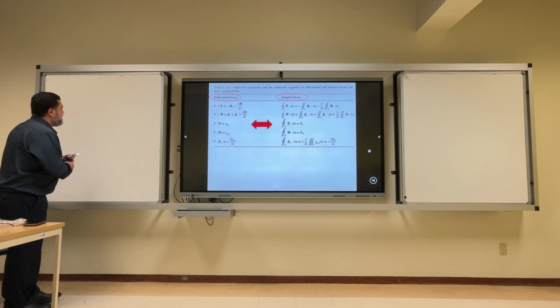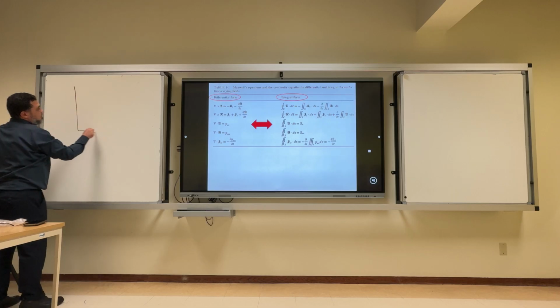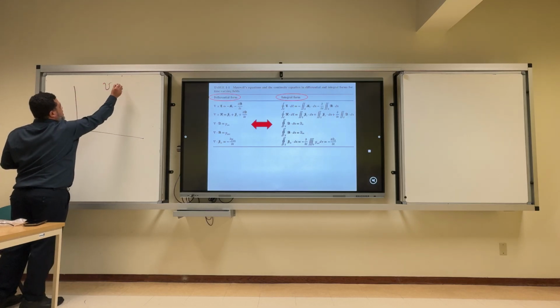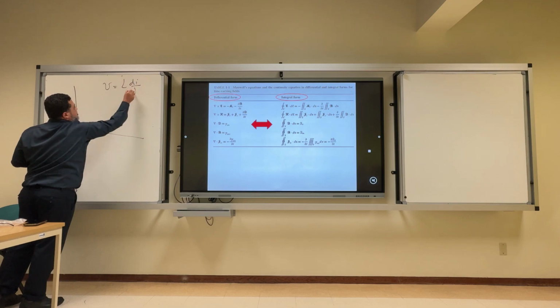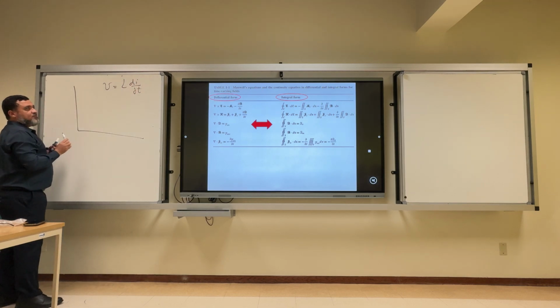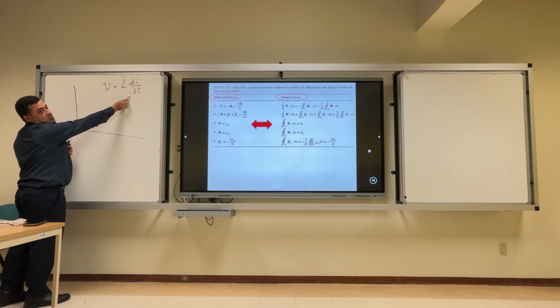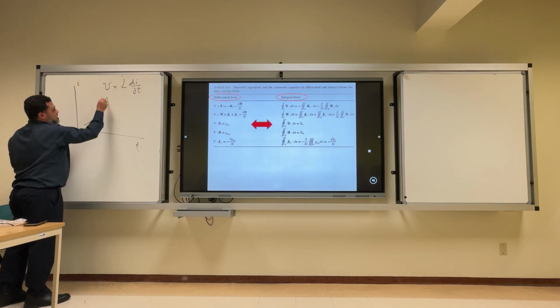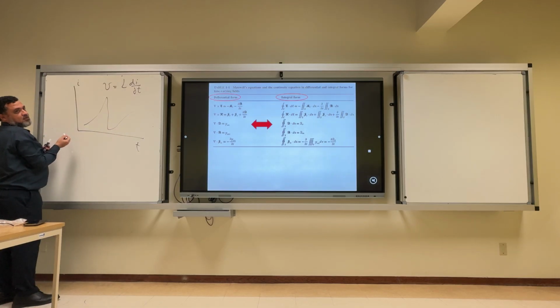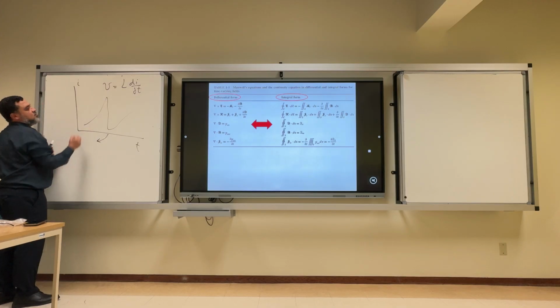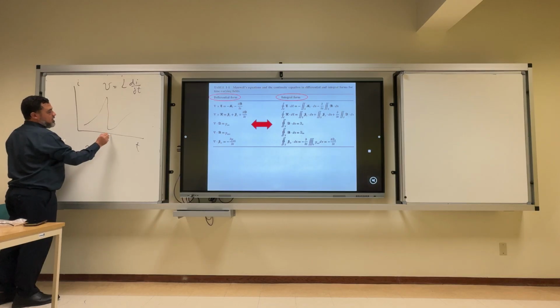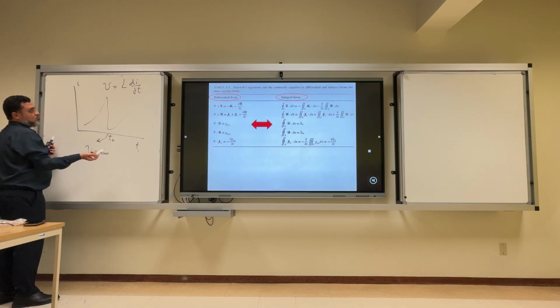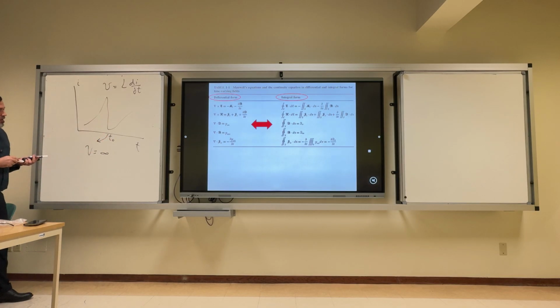So if you look, say, at the relation between, do you remember the equation, the voltage across the inductance, L dI by dt? Look at this equation. Can we have a sudden change in the current? Meaning, can we have I versus t to be something like this? Can we have this? Why? At this time, what is the voltage? Infinity. The dI by dt here at this time is infinity. So it will give a non-realistic solution.